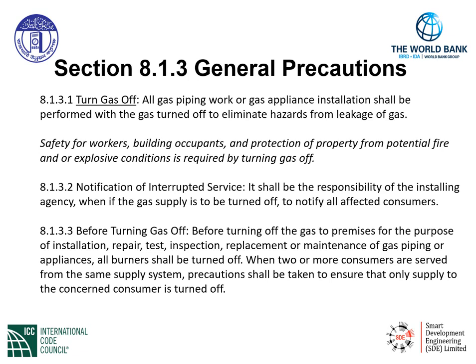This is very important here because not only do we have to protect the workers working on the gas line, but also the building occupants. We do not want to remove any fittings, any valves, any other components on the gas line without properly turning the gas off. In other words, when you turn the gas off, the function of purging, bleeding the gas out of the lines completely before working on certain sections of the gas piping system is important.